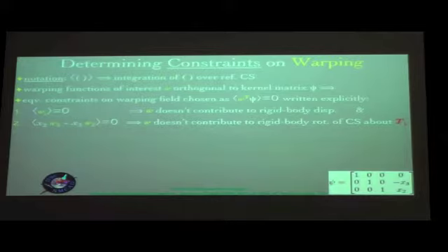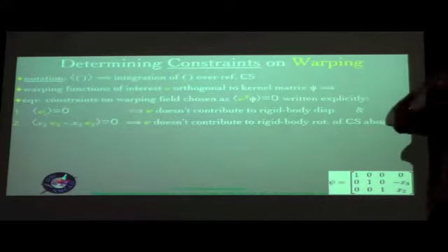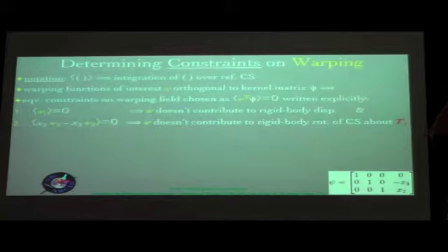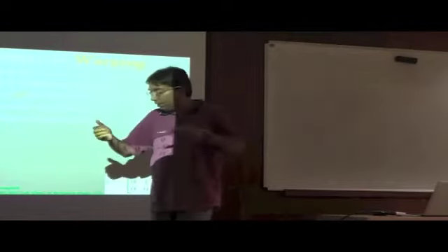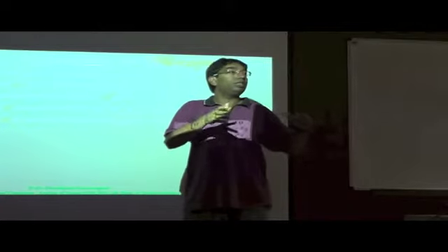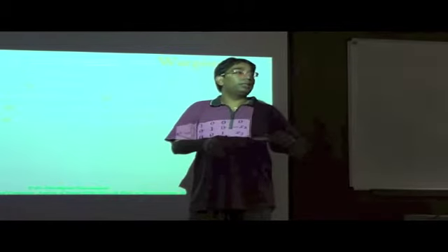But remember that they are all in terms of the constants C1, C2, which are all functions of x1. So once again I stress that different cross sections can have different so-called rigid body like motions. That's why the qualification "like" is very important, because 2 different cross sections can have different rigid body like motion. So therefore the beam as a whole is not moving as a rigid body. There is still strain associated with it. That's an important thing to remember.